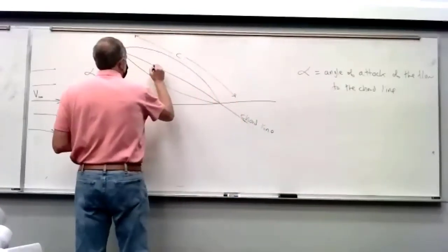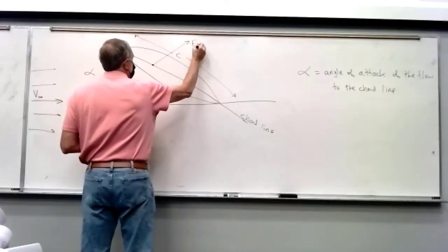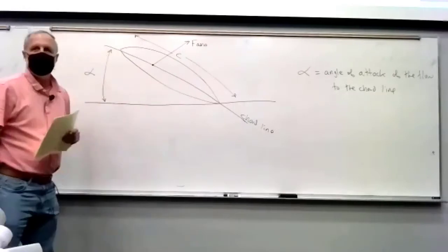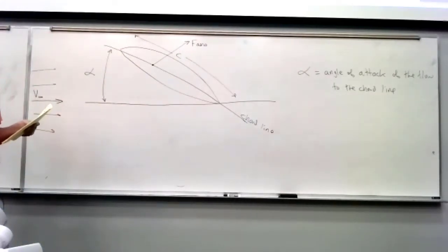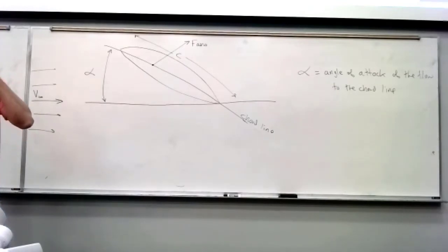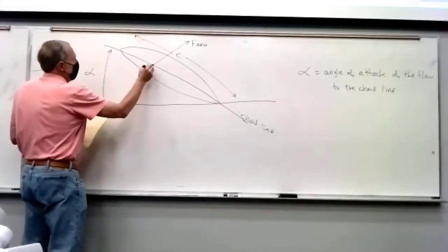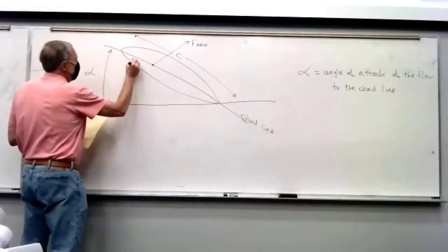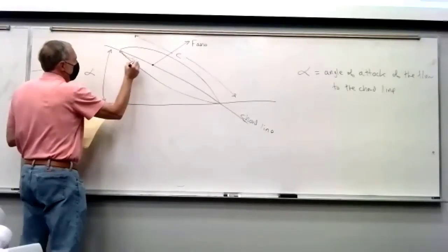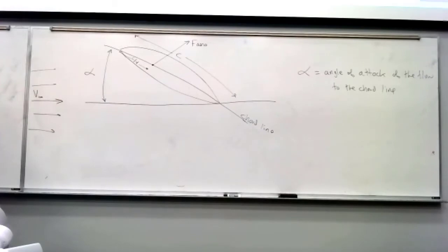And so we get an aerodynamic force, we'll call it F arrow. Is that perpendicular to the chord line? It's not in any particular direction. So if it looks perpendicular, it's not. But these directions are important. Oh, by the way, I'm drawing this at a distance 1/4 of the chord back because it turns out that's a really good place to measure the force at.